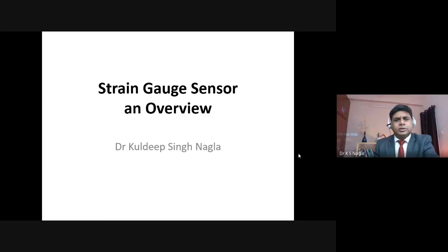So this presentation is about the strain gauge sensor and overview. This transducer is used in industry, in process control and instrumentation, in general measurement. And it is very commonly used for measurement of a force, for measurement of a pressure, for measurement of some other parameters such as the load. So sometimes it is also termed as a load cell in industry.